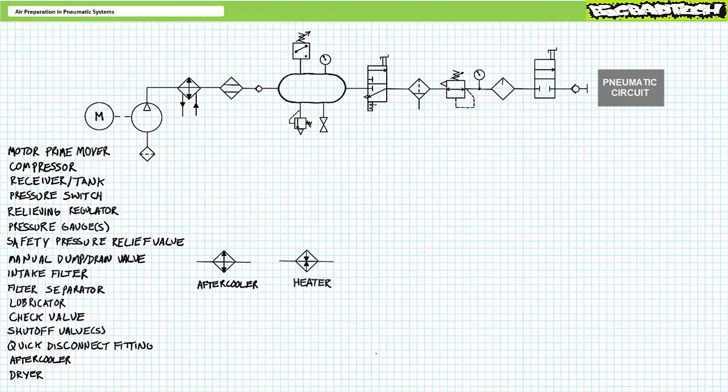You recall, this is essentially the opposite of a heater, commonly found in hydraulic systems intended for cold weather operations. Heaters are schematically illustrated as diamonds with arrows pointing into the oil passing through the center, indicating heat is being added to it. Aftercoolers found in pneumatic systems, in contrast, remove heat, thus the arrows point away.